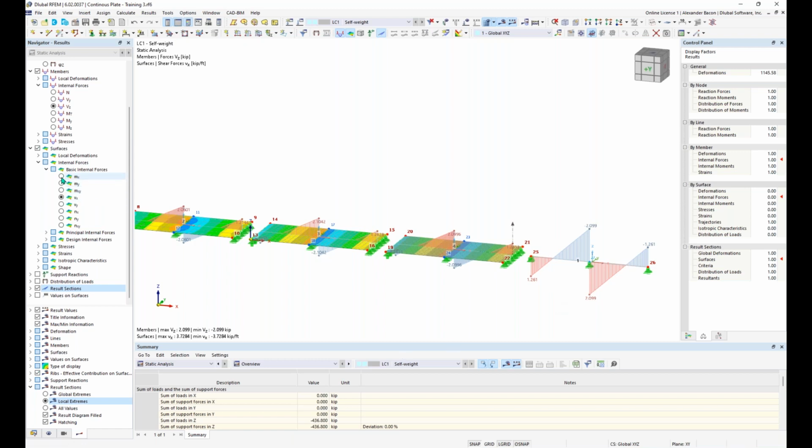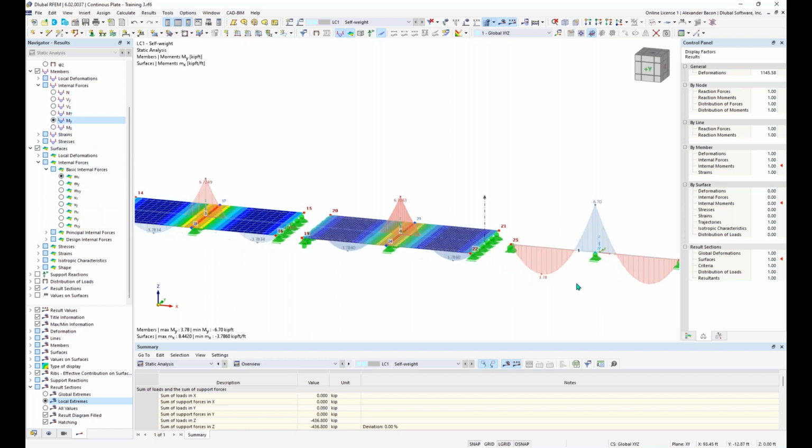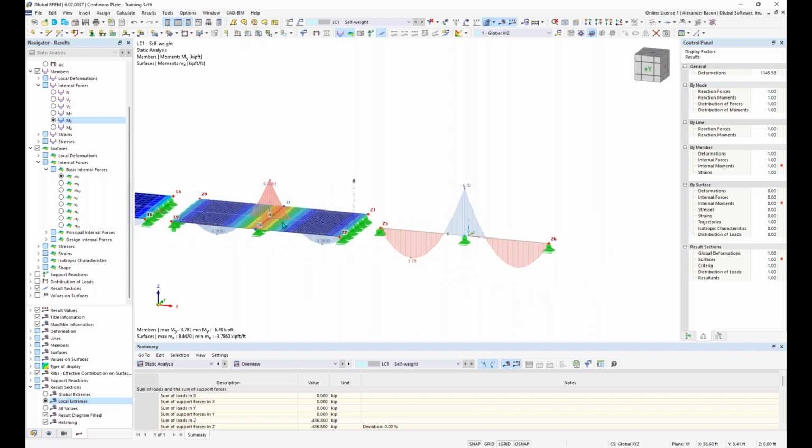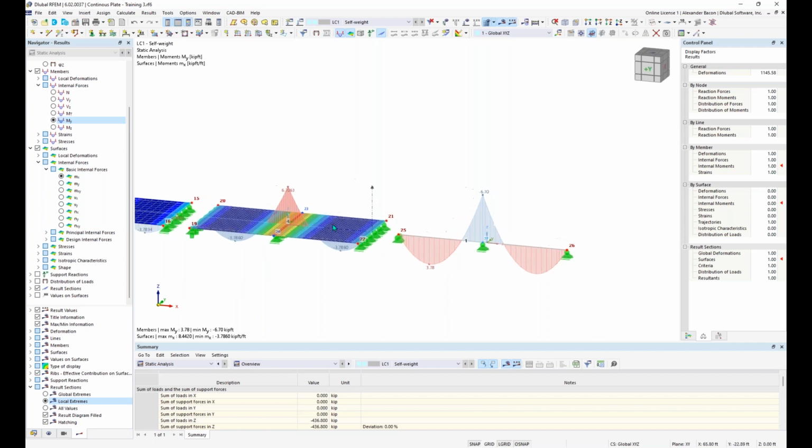And so now if we take a closer look at something like bending moments, we can see how the results compare between the beam here and our plate here. So obviously the surfaces should match the beam. And this shows how important it is to make sure your FE mesh is fine enough, because you can see the super-fine FE mesh here is the closest comparison.